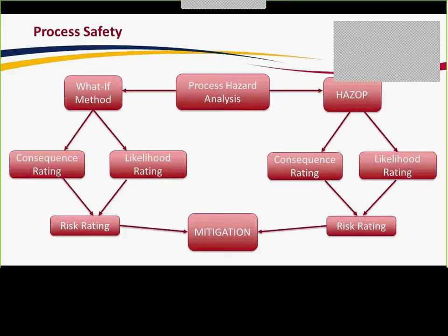In terms of inherent safety, our plant is a small-scale pilot-sized plant, so it is more inherently safe than a large industrial application plant. In addition, as you're about to hear, we have incorporated 2 of our process units into 1 unit. We combine the methanol evaporator and the process coil to form 1 unit, which in turn makes our process more inherently safe.